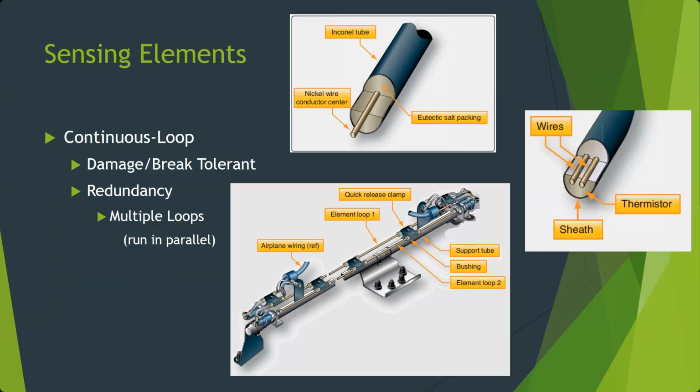So heat or metal parts in a warm area concentrate heat and transfer heat directly into whatever touches them. So if this tube and these brackets are warm, and these loops are made to sense heat in the air, if you don't have those rubber grommets there, you're going to get hot spots everywhere one of those little metal things are. So that's a common failure point, is you'll be getting indications and you'll realize that one of those grommets fell out, or the grommet wore out and fell apart.